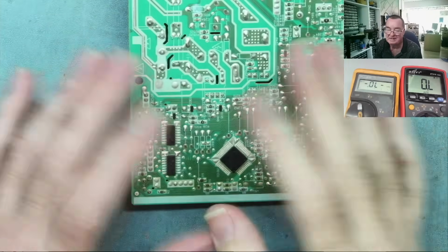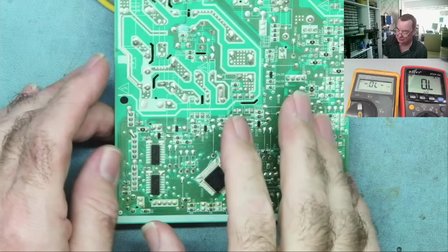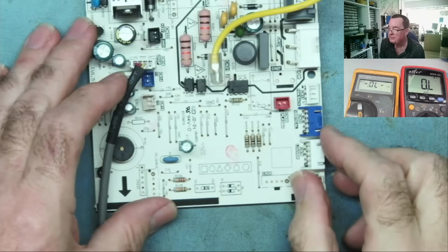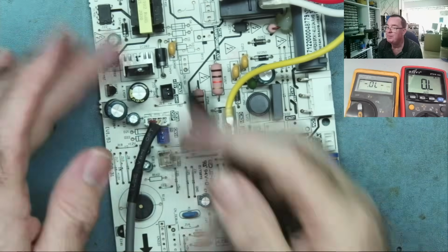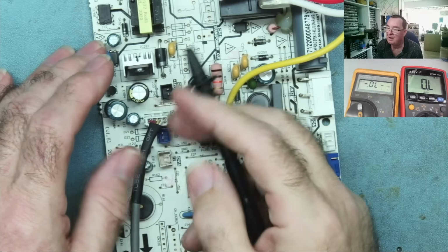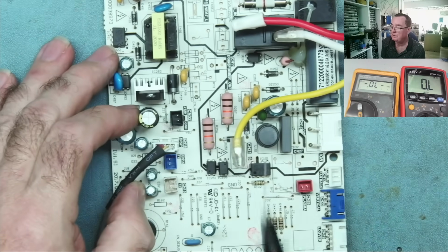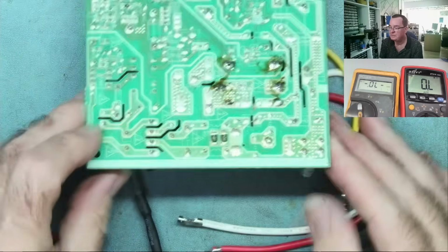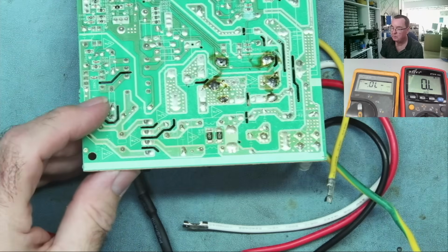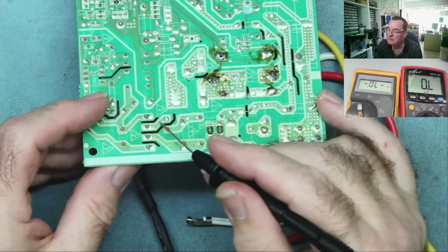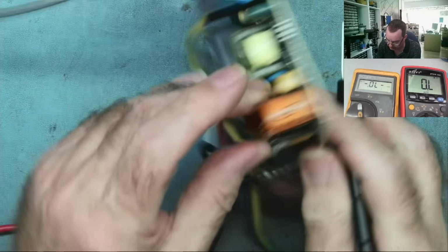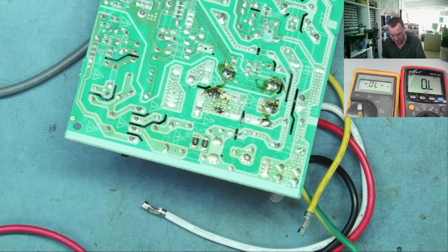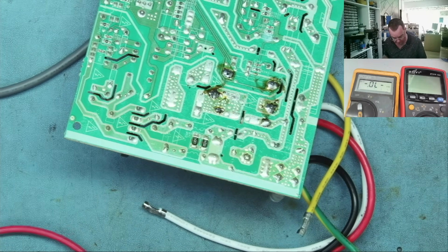Everything tests okay that I can test. Bear in mind the stuff that I can't test. The only thing left really is to power it up to see if I have this power supply running and to look at this. Okay, so power it up. Let's see how it's wired. Well, we can see the two AC inputs here. Okay, and that one there comes through the NTC, of course. So don't need that meter anymore.